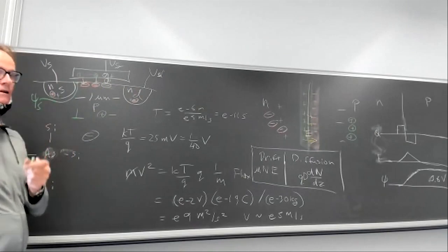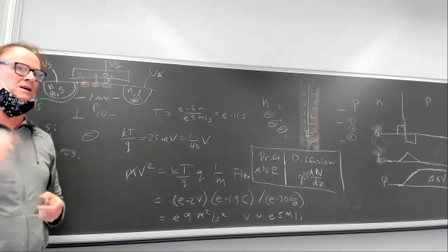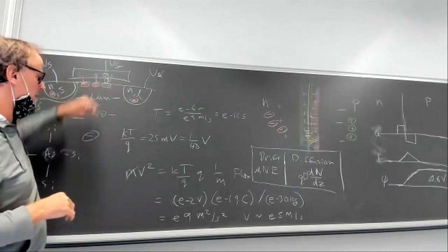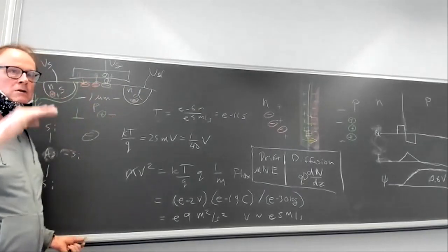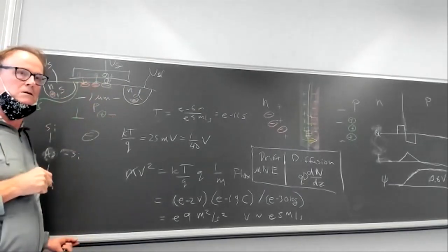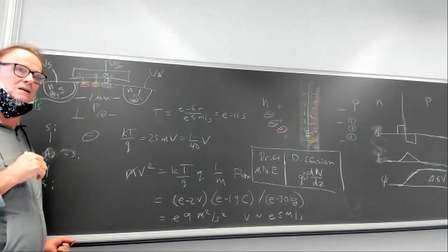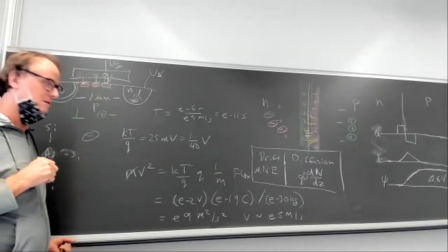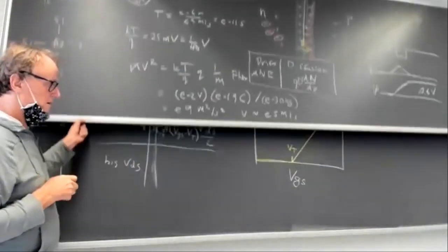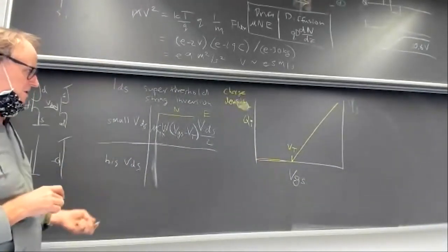For logic circuits, you want the N and P FET thresholds to be about the same. So they always do this little implant of a certain amount of donor and acceptor just to adjust the threshold to the good level for logic circuits. Is it clear? Okay, so that's what the charge density looks like as a function of the gate source voltage.